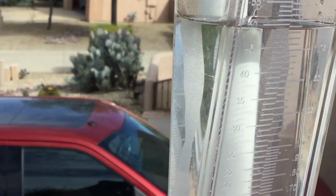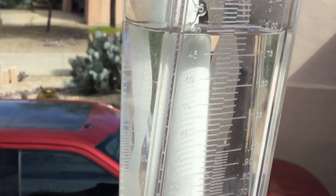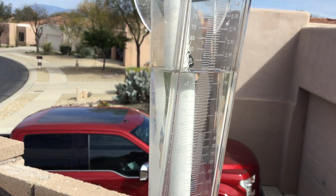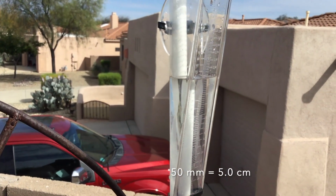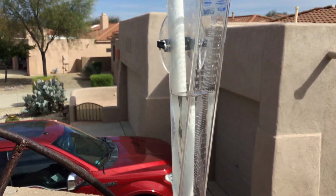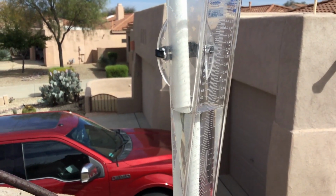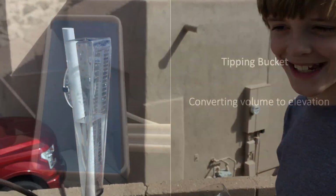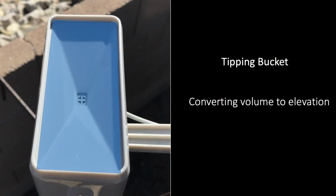Let's see. We're right at 50 millimeters, actually just a hair under, but close enough to demonstrate that the method that we're using to use weight to check the accuracy on these instruments is valid. Nice job, Joey. Thank you, Dad. Right on. Now that I have a proven method to convert mass of water to volume and depth, I can use that same method on my tipping bucket rain gauge.